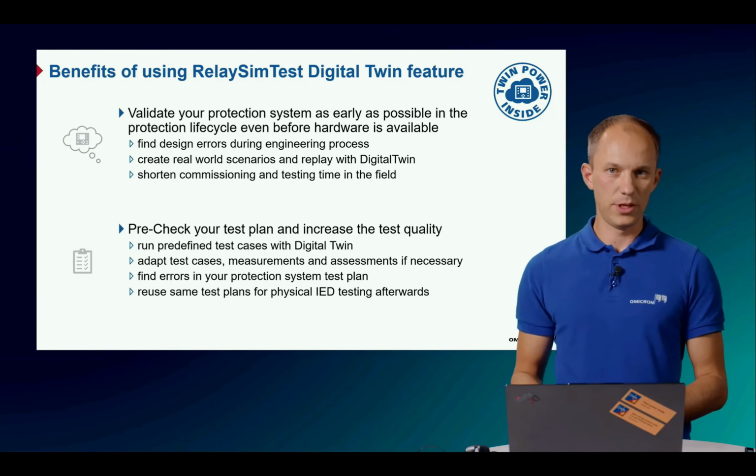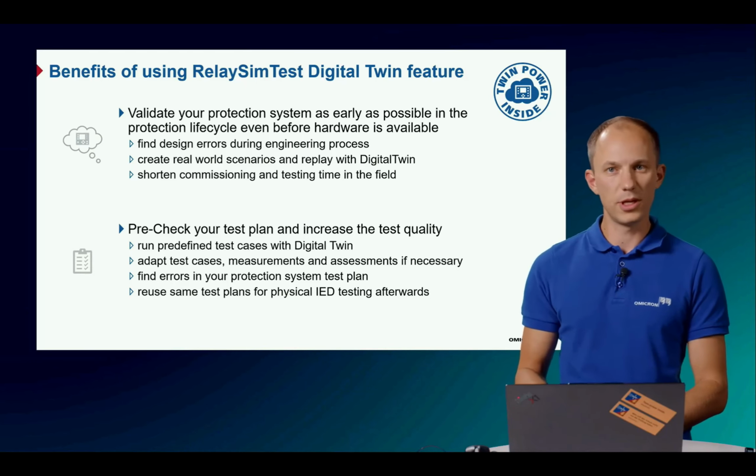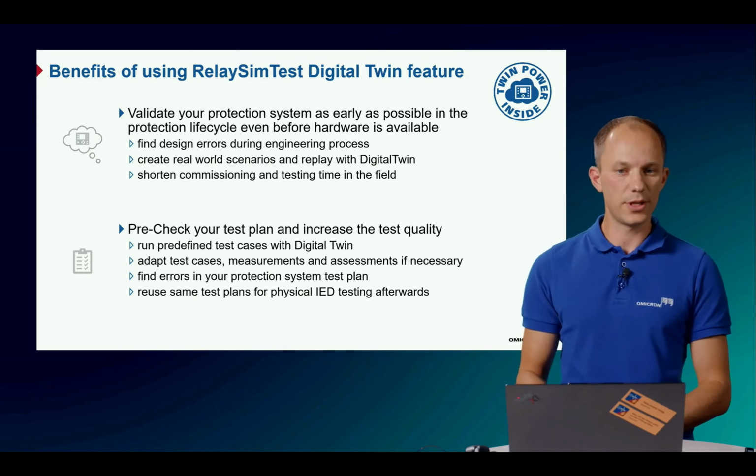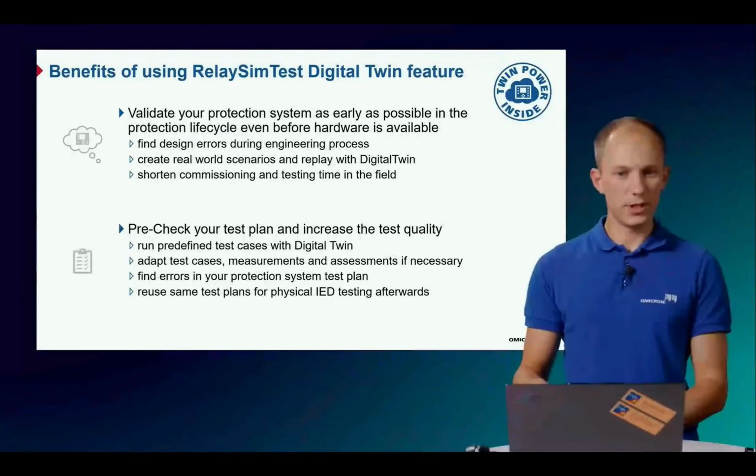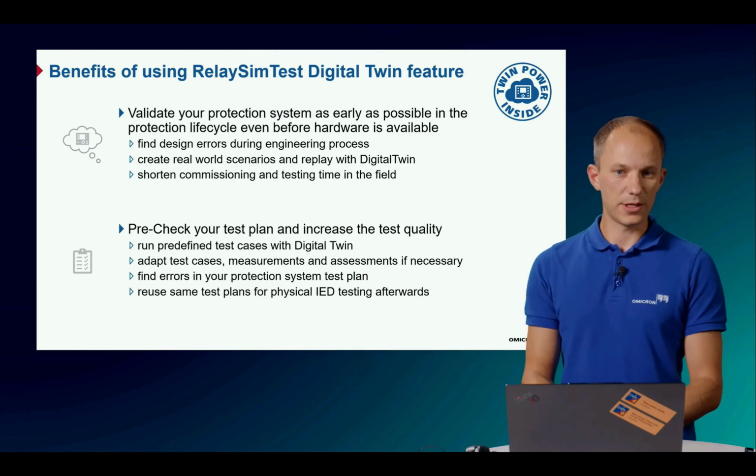Maybe you did some wrong measurements, you forgot maybe a binary signal that you need for the test. So you can adapt whenever you need your test plan. Then you could also find errors in your protection system test plan, and you can reuse exactly the same test plan that was used now in the virtual environment for the physical IED testing afterwards.